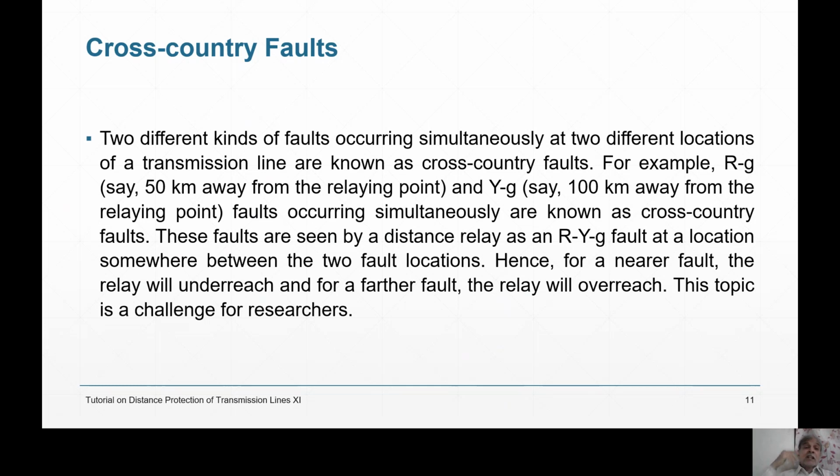Another fellow found another way. If there were reactance alone, then overreach would be large because overreach is due to inductance. But if the fault occurs after the capacitor, the overreach will reduce because the capacitor will reduce the overreach.